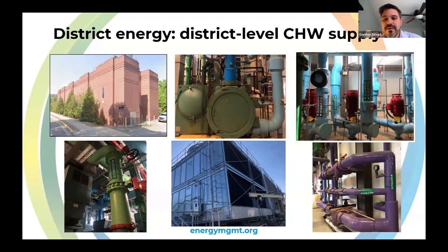Another area which can often be overlooked is such a simple thing as having a good cleaning program for your cooling towers. That sort of preventative maintenance can easily be dropped out. For a campus of our size, and for any significant campus, you can't really think of commissioning in the recommissioning or retrocommissioning mindset of let's do this building every 5 years or whatever, because you've got way too many to get through. I think it's much better to think of it from an ongoing commissioning perspective and mindset. And with ongoing commissioning comes preventative maintenance.